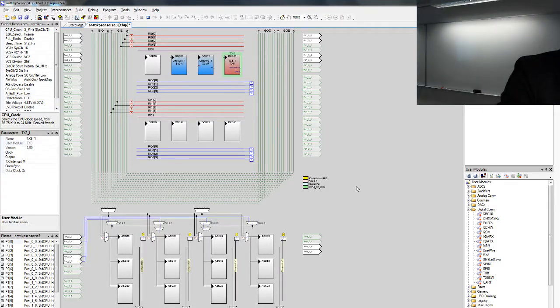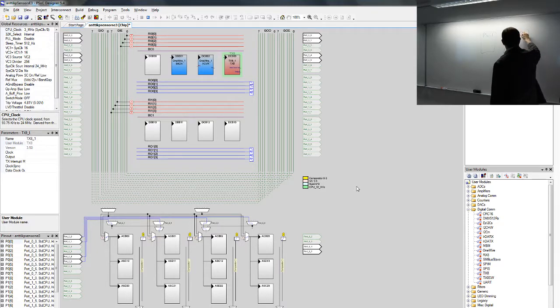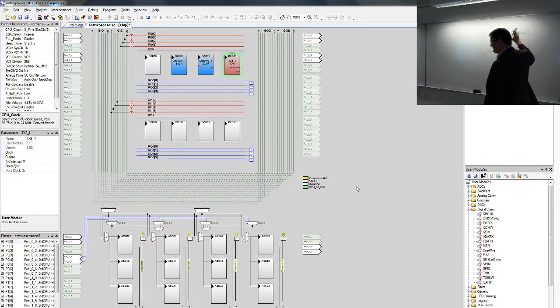And then a hint about the wiring. So PSOC 1, and that's the PSOC 5 board. There you have the TX, RX, and ground. Same thing there, you have the ground, RX and TX. So remember to hook up the ground wire, so that's the reference for the signal, and then this one transmits and this bridge actually receives. So this is configured as a similar DTE device as any other.